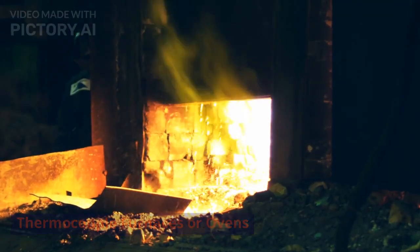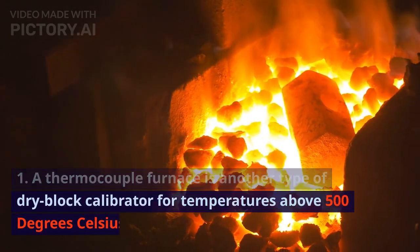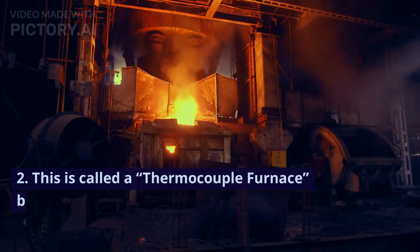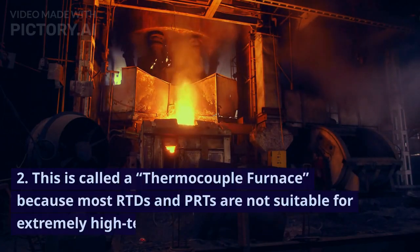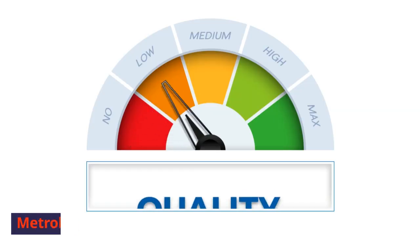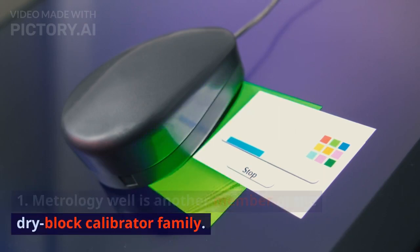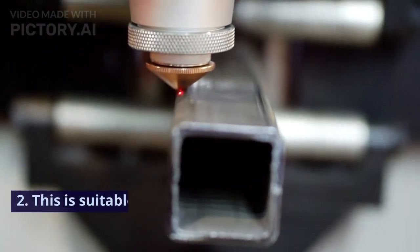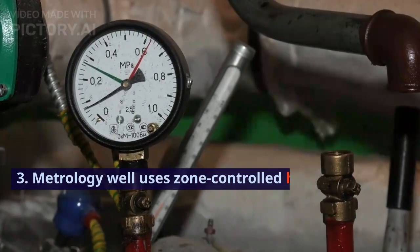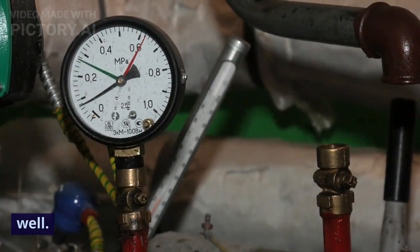Thermocouple furnaces or ovens. 1. A thermocouple furnace is another type of dry block calibrator for temperatures above 500 degrees Celsius. 2. This is called a thermocouple furnace because most RTDs and PRTs are not suitable for extremely high temperature ranges. Metrology well. 1. Metrology well is another member of the dry block calibrator family. 2. This is suitable for high accuracy measurements. 3. Metrology well uses zone-controlled heaters for better axial and radial specifications than dry well.